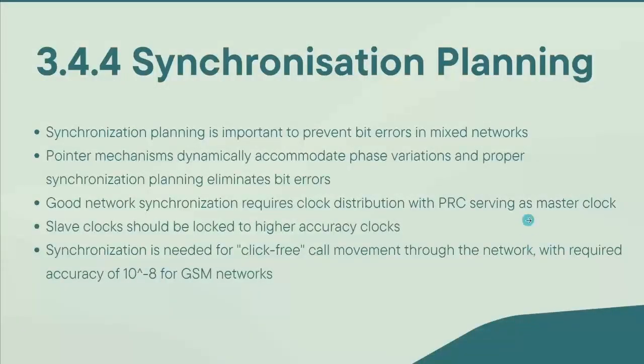So moving on to the synchronization planning. Synchronization planning is also important to prevent bit errors in the mixed network. A buffer mechanism dynamically accommodates phase variation, and proper synchronization planning eliminates this error. Good network synchronization requires a clock distribution with a primary reference clock serving as the master clock, and slave clocks should be locked to a higher accuracy clock. Synchronization is needed for slip-free flow of traffic throughout the network, which requires accuracy of 10 to the power of -8 for a GSM network.